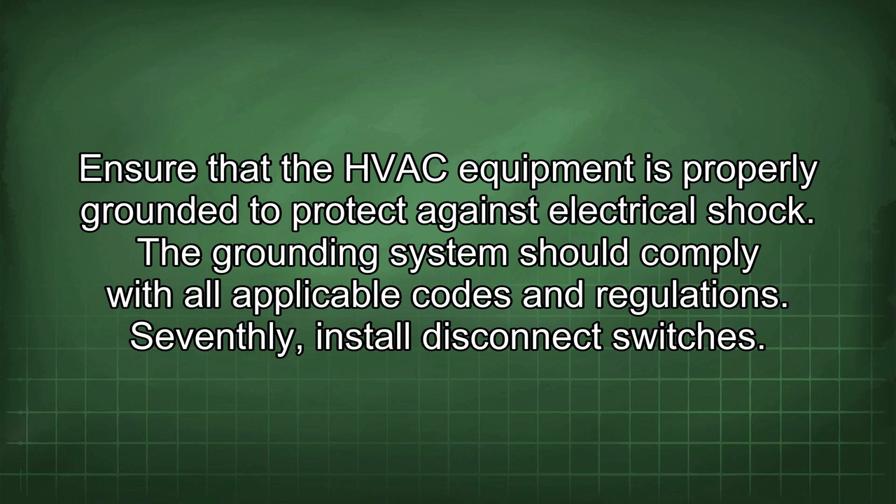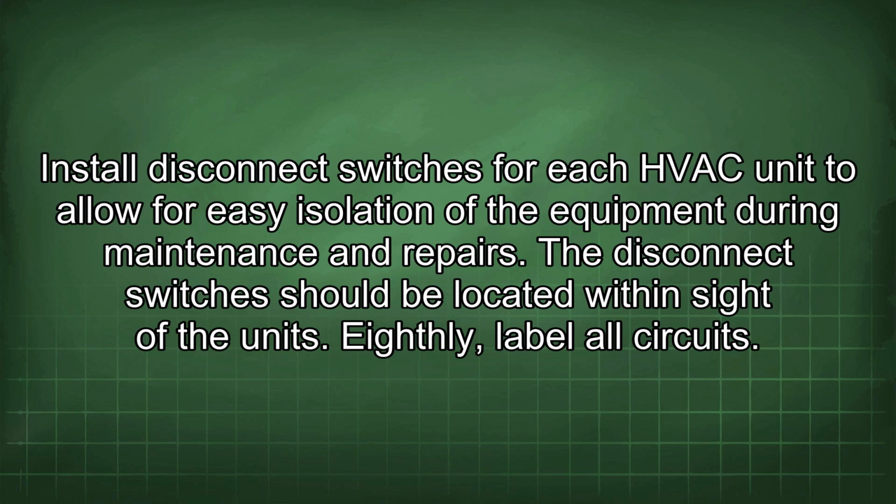Seventhly, install disconnect switches. Install disconnect switches for each HVAC unit to allow for easy isolation of the equipment during maintenance and repairs. The disconnect switches should be located within sight of the units.